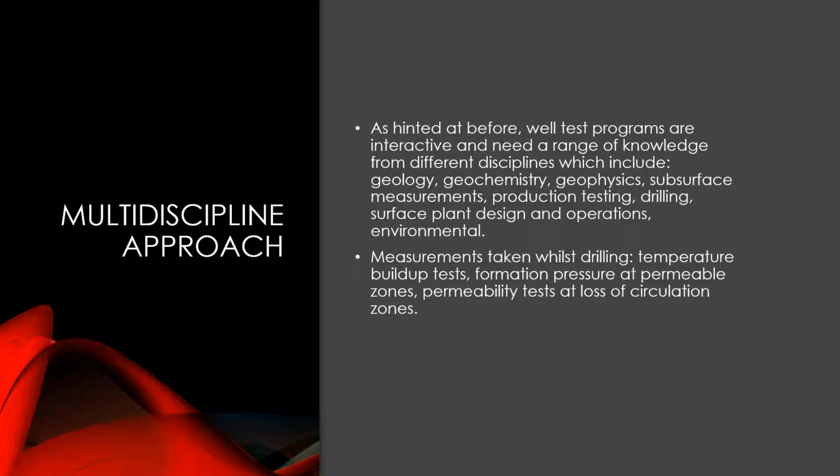Measurements taken whilst drilling: temperature buildup tests, formation pressure at permeable zones, permeability tests at loss of circulation zones. Now, there are a number of tests that are possible before actual drilling. There are tests that happen while you drill, and then there are tests that happen during production, or during the first batch, let's say, of production. And even these tests themselves have to be designed and studied very thoroughly by this multidiscipline team that is looking at this well.